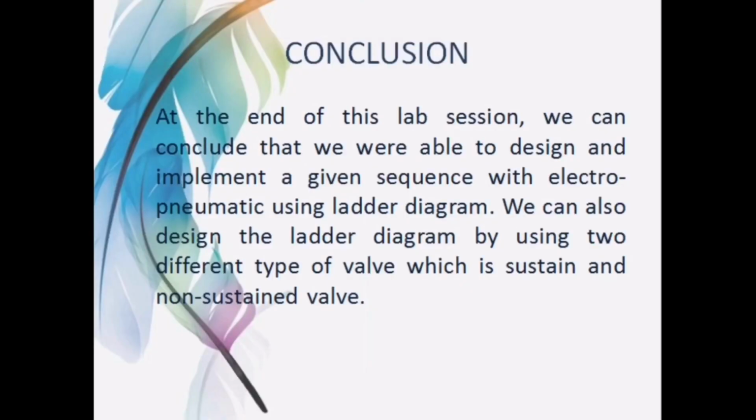At the end of this lab session, we can conclude that we were able to design and implement a given sequence with electro-pneumatic using ladder diagram. We can also design the ladder diagram by using two different types of valve, which are sustained and non-sustained valves.